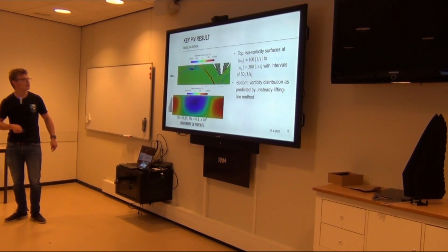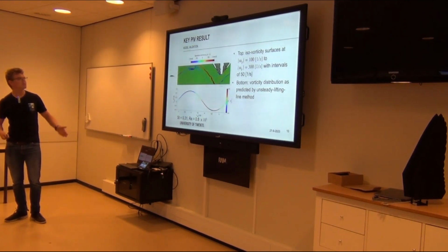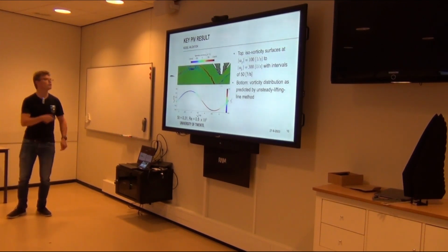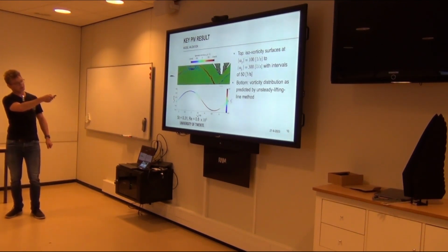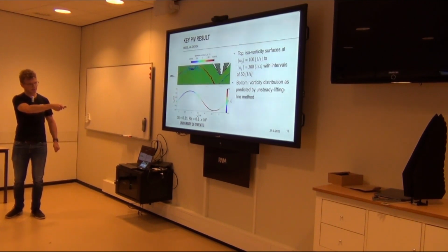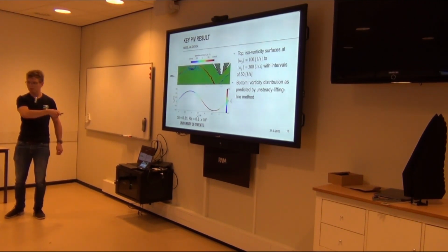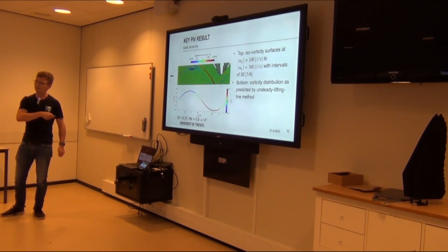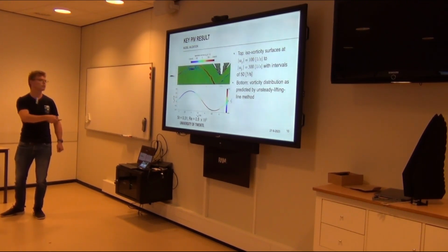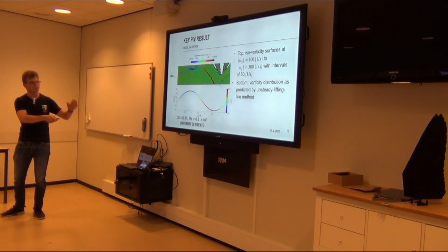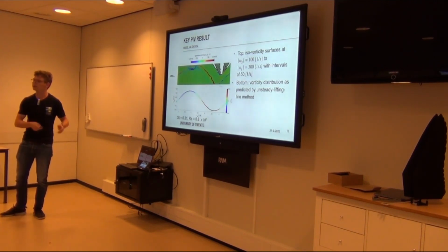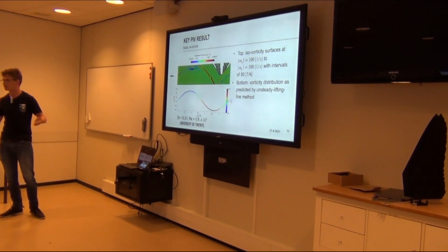And if we look at a cross section of it, you can see that it already, again, corresponds fairly well. So on the top you see an experimental result, and on the bottom you see an idealized result where I took the liberty of plotting the strength of the vortex sheet on a sine. So this is not our model, but this helps you see is there something that looks like an inverted von Karman vortex sheet, for example.